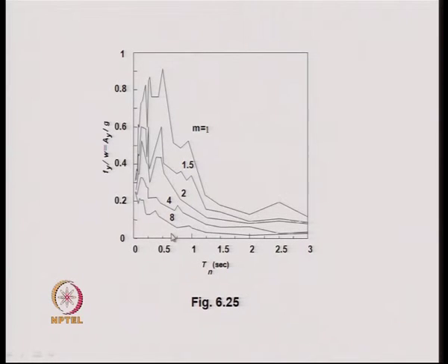We can see the inelastic accelerations for different values of mu plotted here, and one can see that for higher values of mu, the value of the spectral acceleration is drastically reduced compared to the elastic response spectrum.